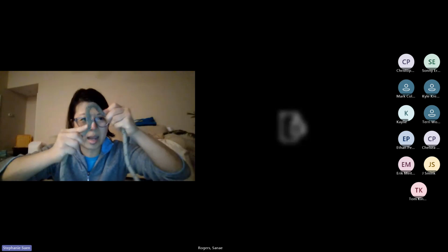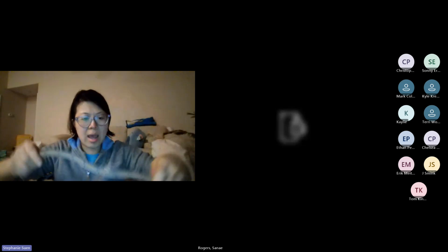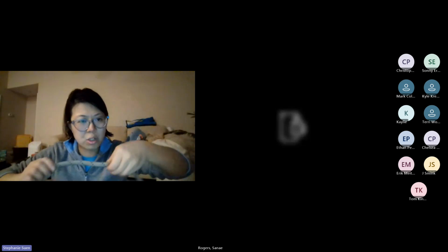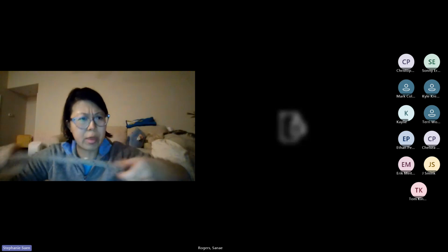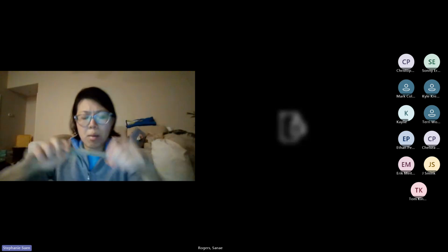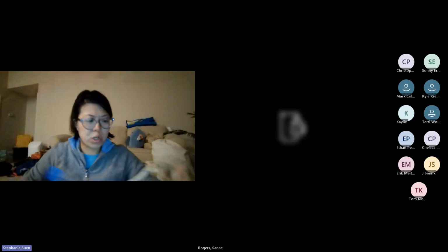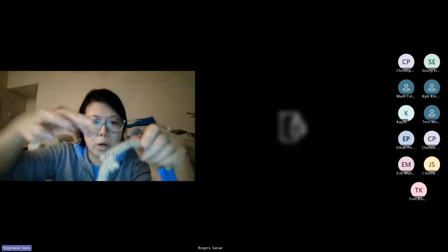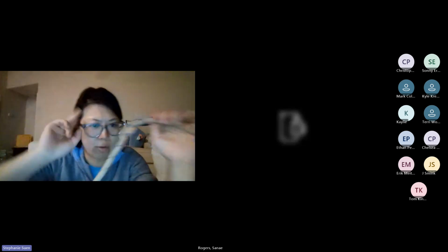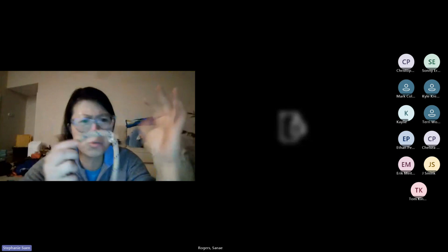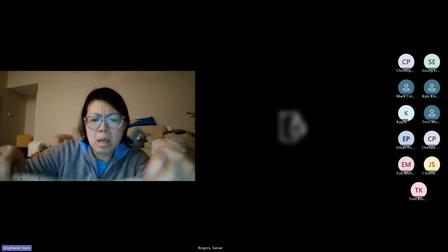Something's wrong. It hangs up right there, and that's something you want to just feel around, and you're like, oh wait, there's actually something wrong with that, right? So you don't want to be using those core shot pieces of rope. That's a place where you want to maybe cut that, and now you have two smaller ropes, or maybe you just retire the rope completely, right?